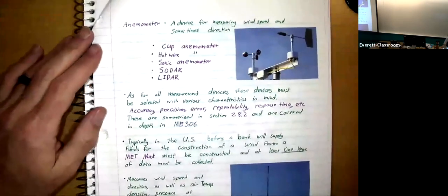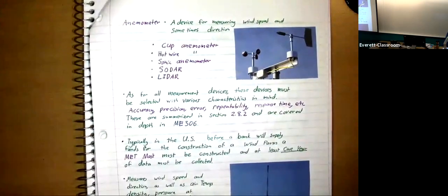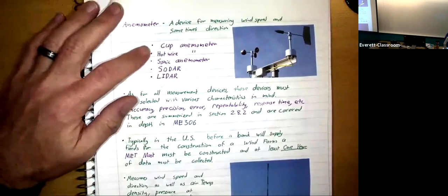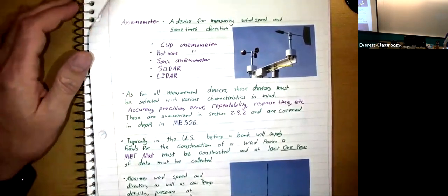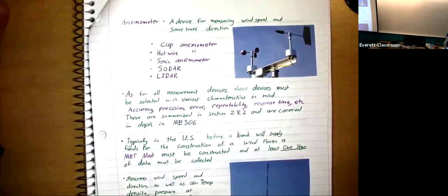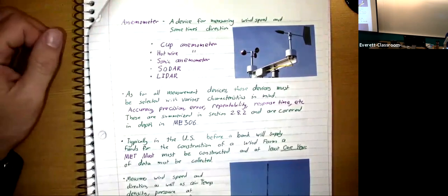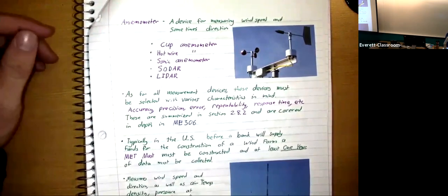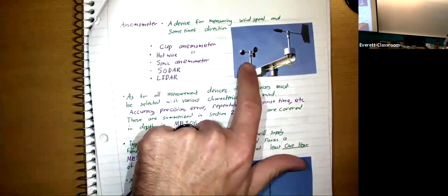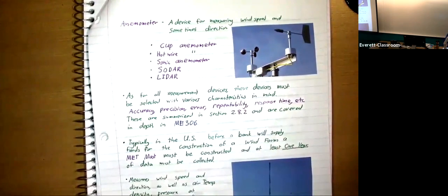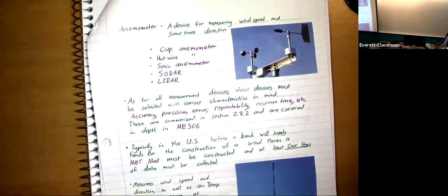And so there are lots of devices that we have for collecting wind data. The most common, and the one that the banks like the most, is the cup anemometer. The anemometer is just a big fancy word for a device that measures wind speed. And they also usually measure direction as well. It's a pretty straightforward device. It's made of these cups. And when air blows against them, the drag on one side of the cup is different than the other side. And so they'll rotate at a certain speed, and you have some type of probably Hall sensor or some type of sensor that measures the rotational speed of these 3 cups.